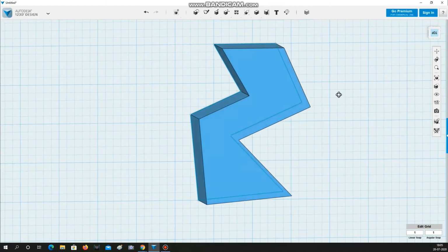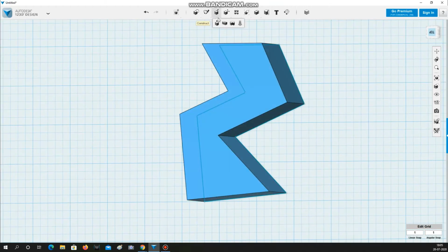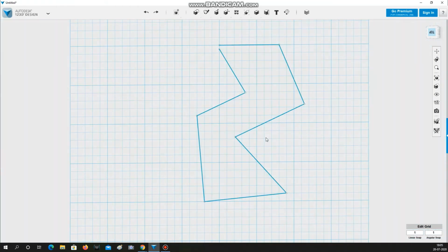So then I would be able to draw any sketch with the help of the polyline, and I would get that. Let's try to add a curved edge on this side. To add a curved edge, I just have to select polyline, but instead of left clicking once and specifying the next point, I should hold the left click until I reach the point where I have to end it, so that I get a curved line.